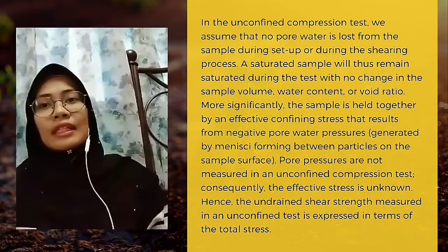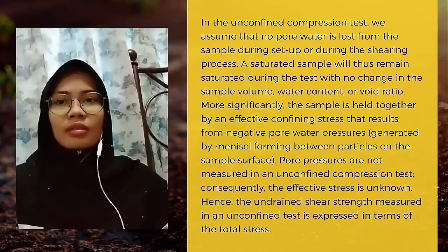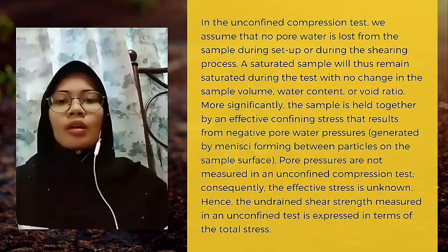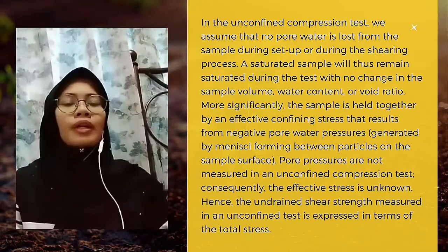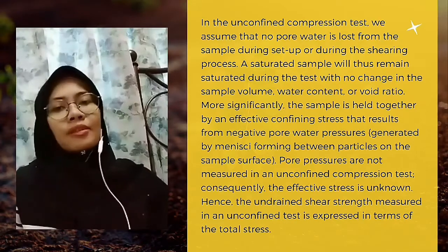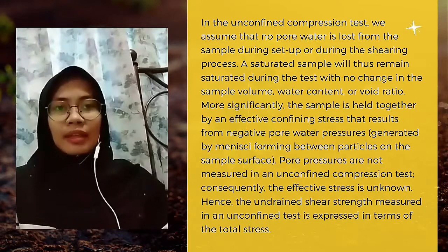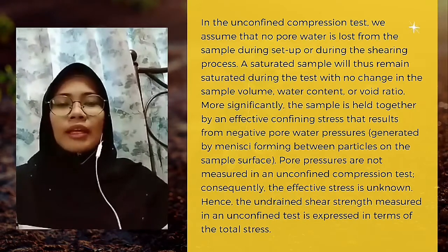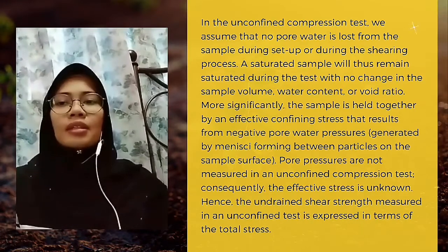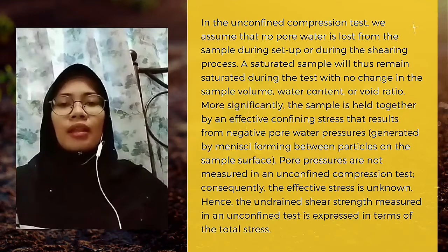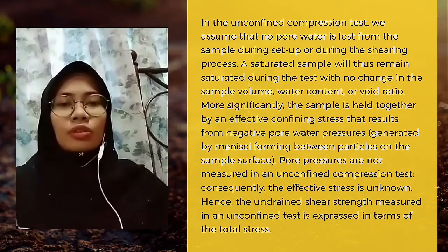So most significantly, the sample is held together by effective confining stress that results from negative pore water pressure, which means it is generated by menisci forming between particles on the sample surface. So pore water pressure is not measured in an unconfined compression test. Consequently, the effective stress is unknown. Hence, the undrained shear strength measured in an unconfined test is expressed in terms of the total stress.